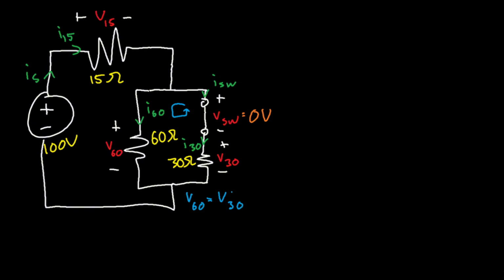Well, what is this? Well, this definition is a parallel circuit. If the voltages are equal to each other in resistors, you got a parallel circuit. And this kind of makes sense, right? What we have here are two nodes. Now, technically, there's a node that separates the switch and the resistor, but we can kind of think of the closed switch as just a path for the current to travel. It doesn't do anything with it. It just allows the current to travel. So what we have here is just wire along this entire thing, and the switch will count as part of the wire of our system.